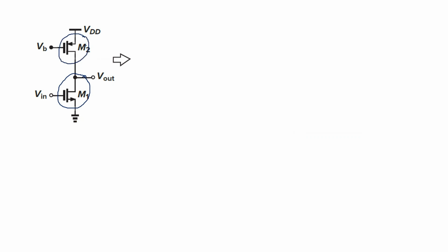So here I have taken the PMOS device. So for this PMOS device, if I want to see its impedance, then this is a bias voltage. This is also 0. And this is your VDD. This is also 0 for a small signal model. And if I am looking from this side, the impedance offered will be R naught. The impedance offered from this side will be R naught 2. So we can also calculate by using the small signal here. So if I am using the small signal here, I need to tell all the points here.